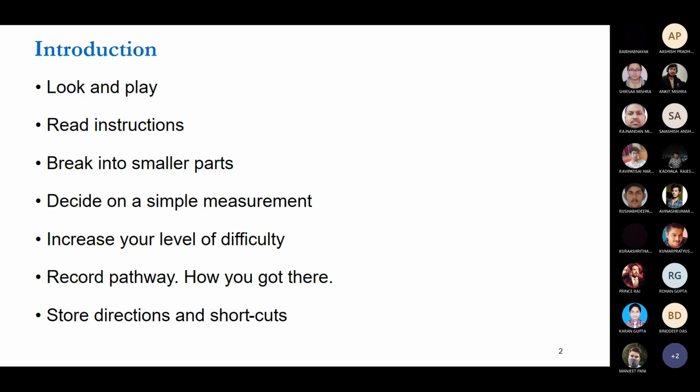There are different types of oscilloscope: non-isolated oscilloscope and isolated oscilloscope. Also there are probes. Probes are the measuring wires of the oscilloscope. A probe has one positive terminal and another negative terminal. If you want to measure the potential difference across a resistor or any other electrical quantity, you connect the positive terminal to one end of that element and the negative terminal to the other end.